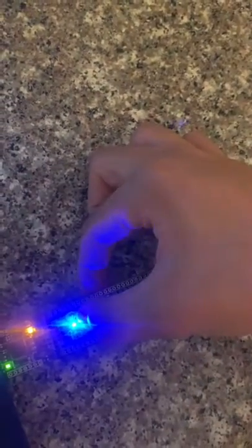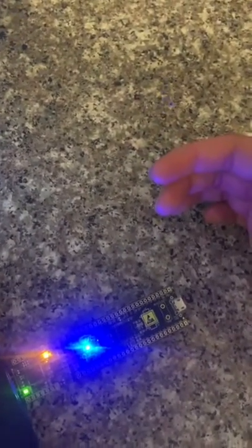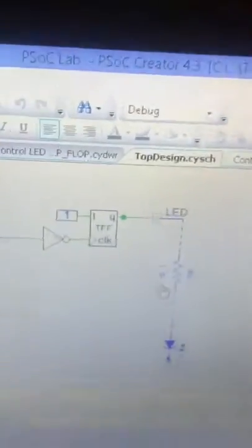So what I can show here is that when I press the button here, and when I lift my finger off of it, it stays on. The T flip-flop purpose is to toggle the LED when you press the button, meaning that whenever the button is pressed, regardless, the LED will either turn off or on depending on the state of the T input.